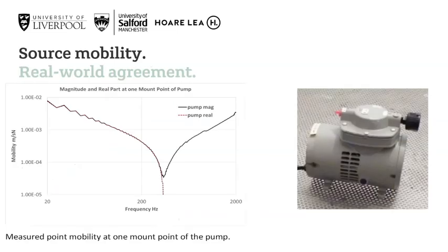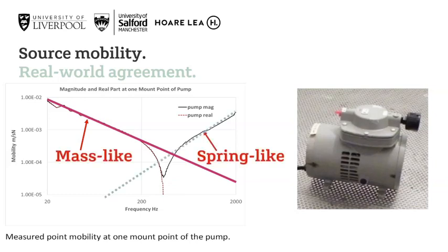And with that in mind, let's quickly return to our results for our famous small pump. We now see that the mobility region above the anti-resonance dip is described incredibly well by a spring stiffness-like mobility of a cantilever. This makes sense since a freely supported element, as it was in the demos, would allow cantilever action to occur once able to do so.